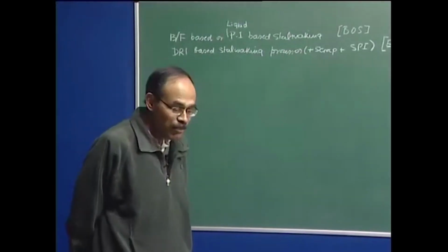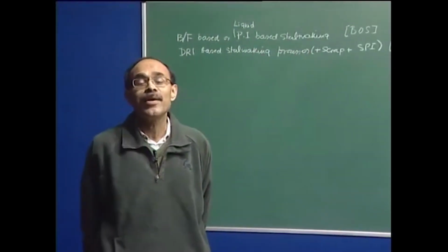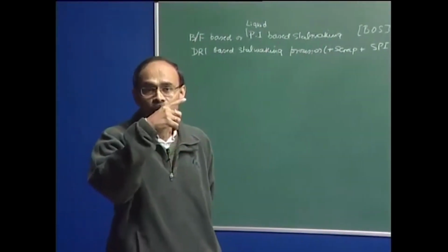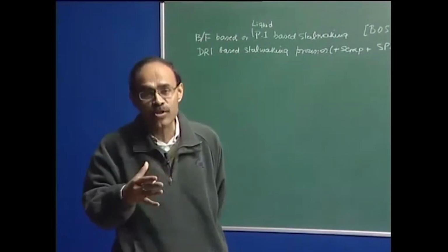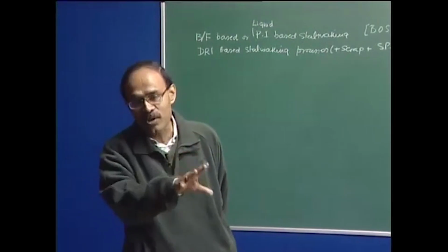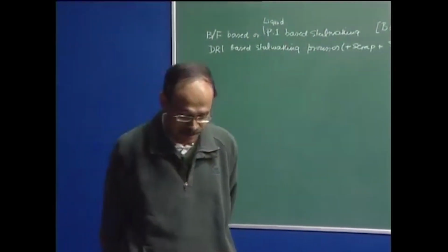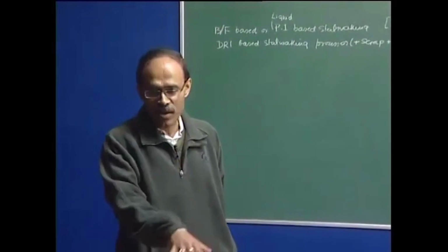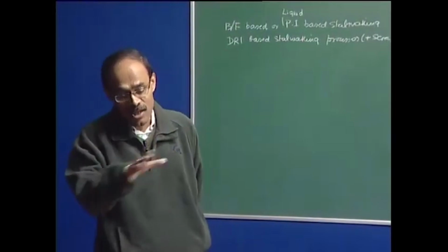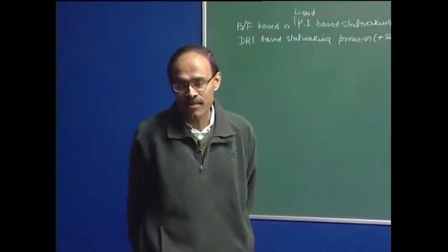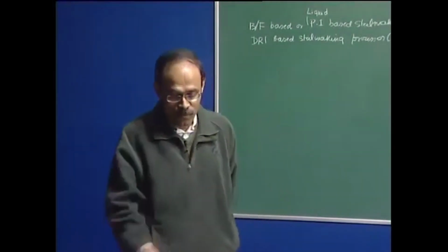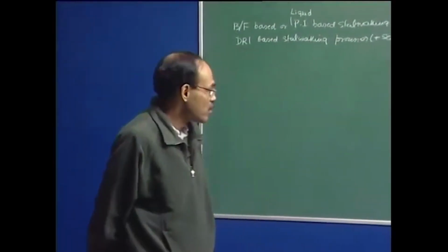Today, a steel plant based on ingot casting with BOF steel making is not sustainable at all, because the rate at which the basic oxygen steel making process produces steel requires an equally fast process to convert molten steel into solid product. Ingot casting is a much slower process. The conversion rate from liquid to solid is much slower in ingot casting than in continuous casting. So, ingot casting is no match for BOS. So, with BOS or BOF, we require continuous casting of steel.